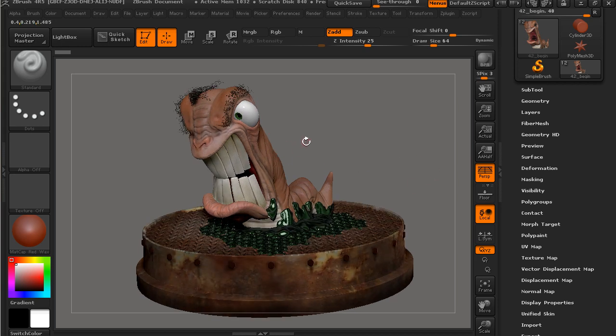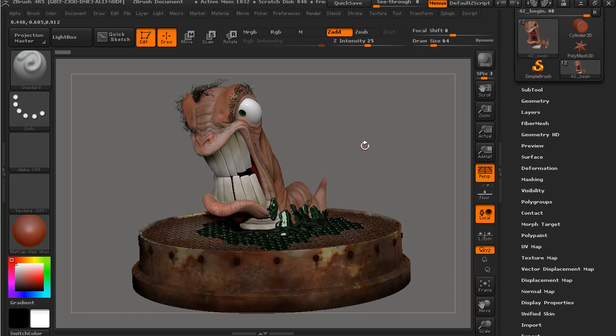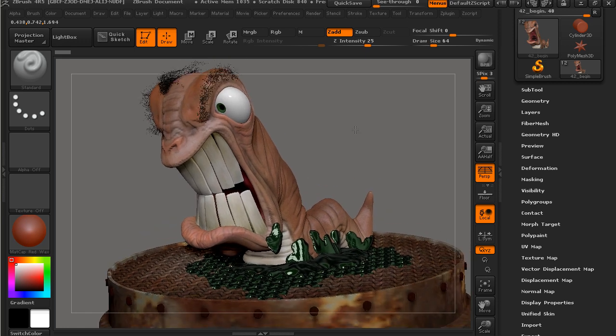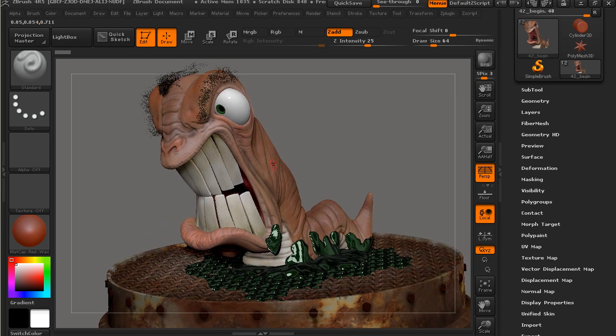So typically if you're building something that's never going to leave ZBrush, you don't necessarily have to have UVs. Sometimes they can help if you have special textures that you'd like to apply in a specific way. But you're doing poly painting, so the texture or the color that you see is not UV based until you want it to be. So in this case, let's say that for this little creature, we want to now create a texture map based on a UV layout. Now, there are different ways to create UVs for this guy.